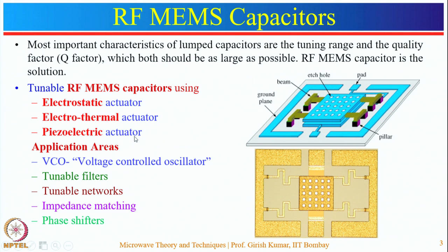It provides linear tuning of the capacitor and a low driving voltage. So, these are the advantages of the piezoelectric actuator. When the bias voltage is applied between the controlling pads, the piezoelectric actuator moves down the dielectric of the top metal plate. It provides area tuning instead of gap tuning, because there is no limit on the area tuning.